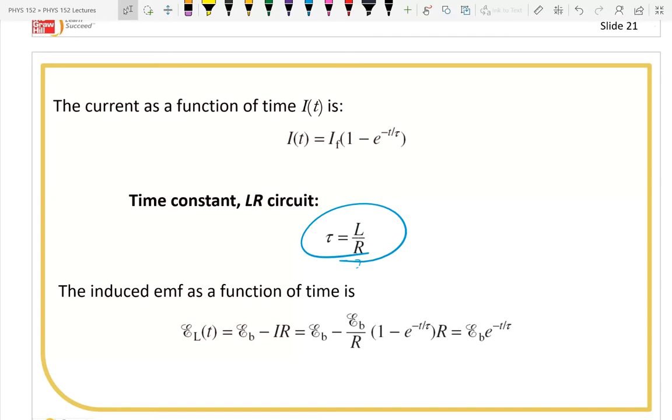And thus, you have some problems with switches for inductors. Oftentimes, they make switches that they call make before break, where you connect across before you break the first connection to avoid that arcing. If you have a DC motor, direct current, and you turn off the switch, you'll see the voltage spike, because you can't stop the current instantly in the inductor. And so it's arcing across the switch as you turn it off.